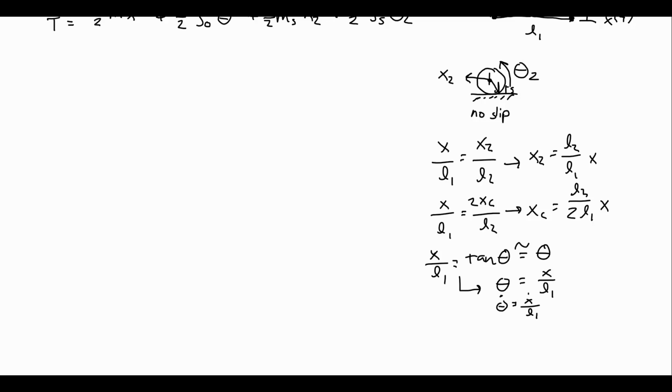So as it rotates, the arc length of rotation is going to equal how much it translates left or right. So we can use a relationship that rs theta 2 must equal x2. Thinking about a full rotation, let's say theta 2 is 2 pi, one full rotation. This is telling us that 2 pi times r, which is equal to the circumference of a circle, is equal to x2. And in a no-slip condition, yes, that must be true. One full rotation means that the center has moved by one circumference.